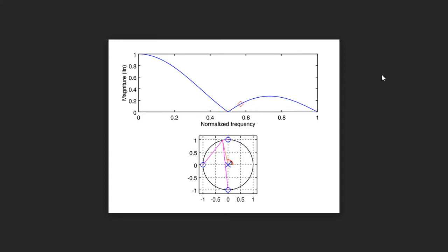So basically, the amplitude response of this FIR system, the 4-point running average, depends only on those distances. And a couple of special points here. We are exactly at the same point where we have a zero, meaning that the amplitude response goes exactly to 0. Same thing at angle pi there. Okay.